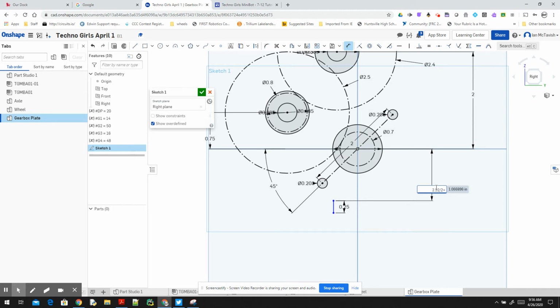And then plus 3/8 of an inch. And that's because I want to pop this down. So the center of my slot will be at the perfect location, but I've got a little bit of leeway then in terms of being able to move this up and down to kind of position things. So that's set up. There's my line. In this set of tools, you can see there's a slot tool. And again, use the search if you don't see it.